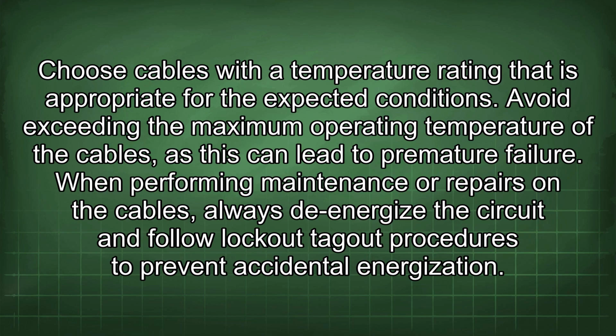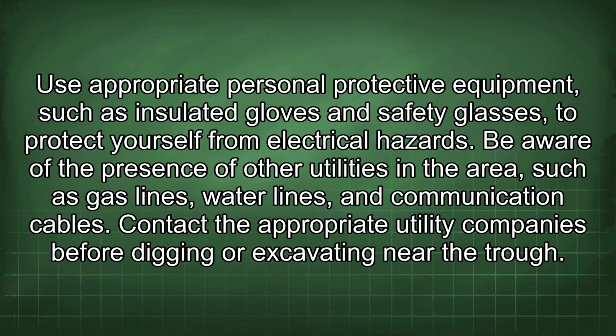When performing maintenance or repairs on the cables, always de-energize the circuit and follow lockout-tagout procedures to prevent accidental energization. Use appropriate personal protective equipment, such as insulated gloves and safety glasses, to protect yourself from electrical hazards.